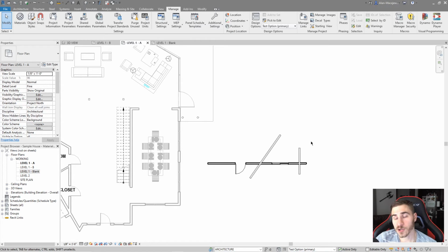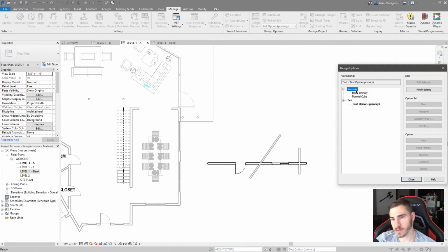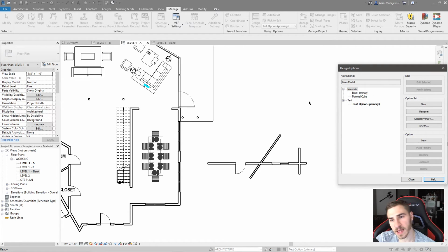So I sure hope this video ended up being a complete guide to what you need to know about design options, because it does kind of have everything. We went over creating design options, looking at them, editing them, adding elements, and then copying elements in between. Again, you can always copy and paste and place in a different design option if you make a new option, because you might on the fly decide, you know what, let's have another test. Well, I can't add these elements back to it, I have to copy them. I have to copy and paste in the same place.